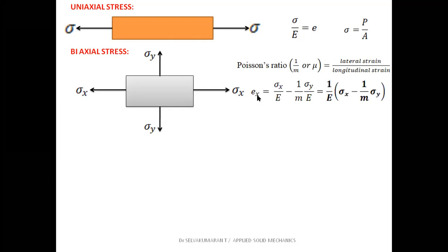Now, Ex represents the strain in x direction. Now we are considering the x direction. So sigma x, the stress in x direction, divided by E, Young's modulus, is the strain, which is nothing but the longitudinal strain in x direction.